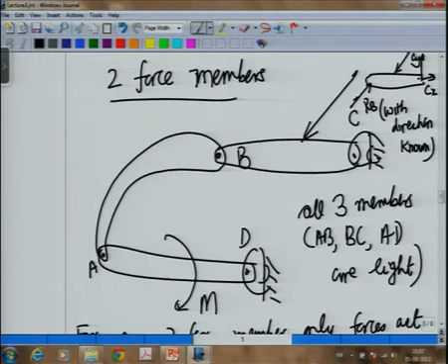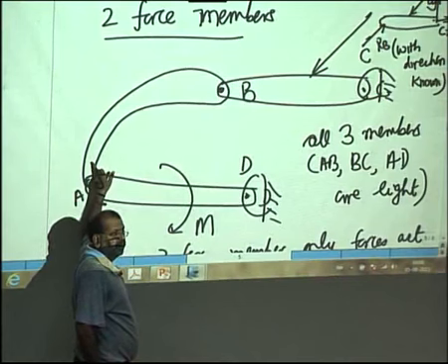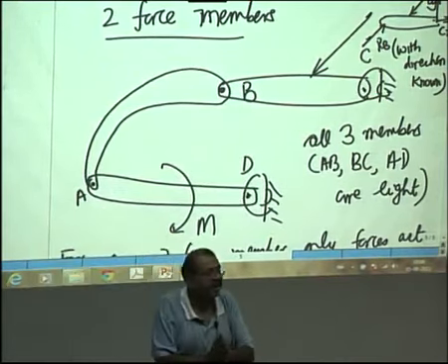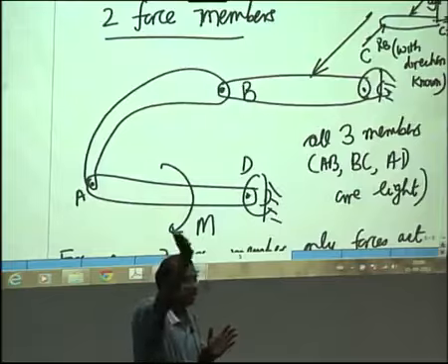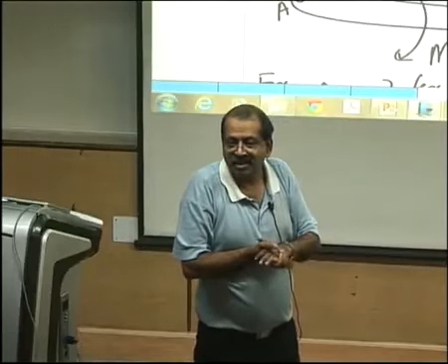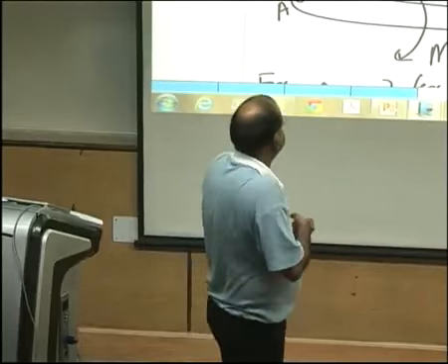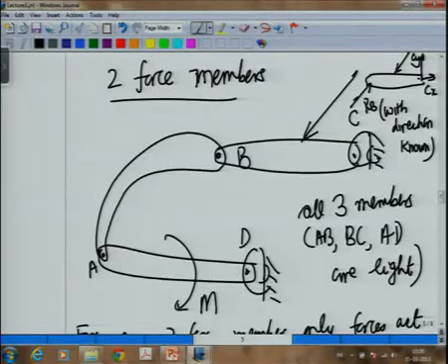Okay. So, you can use two force members to simplify problems, or sometimes even on the same member, if you know it has to act along this given line. And once you do that, you do not need to write equations of equilibrium for the two force member, because they have already been included when you determine its line of action has to be like this. So, that has already been known to you. So, you work these out, and that is how two force member can help you to simplify solving the problems.